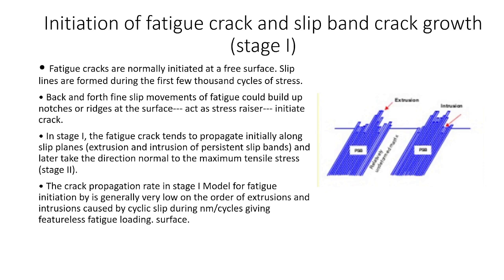We can call it Wood's concept. You can see, when we are shuffling a deck of cards, the cards move, one half of the cards moving in the direction of the applied force, another in the opposite direction. Similarly, you can see these intrusions and extrusions take place in the material when it is subjected to fatigue.